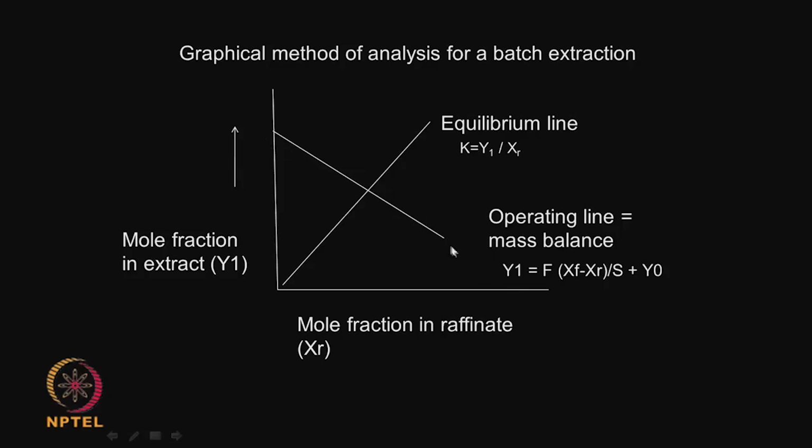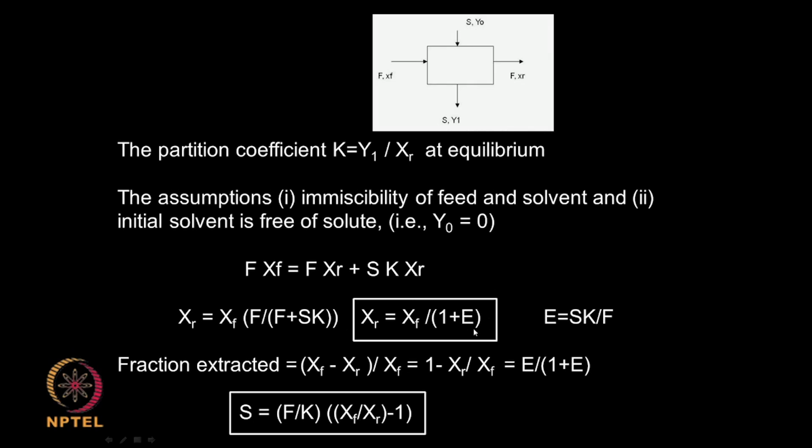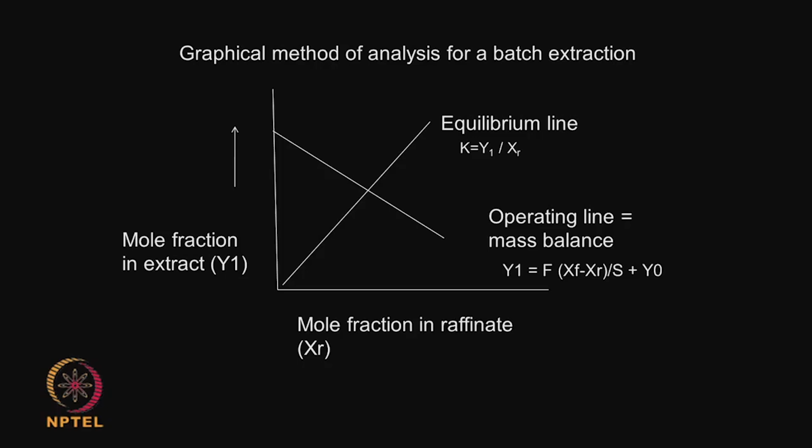So, these two lines will cut at some point, and this is the condition at which you are operating, corresponding to both the mole fraction in the raffinate as well as the mole fraction in the extract. With the help of calculators or computers, we can quickly calculate them. When computers were not there, people resorted to this type of graphical method.